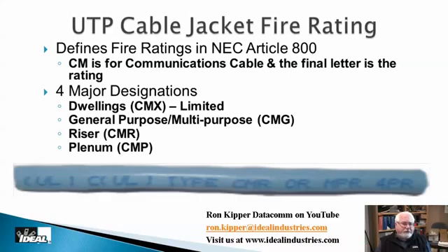Inside of walls, as a general rule, you're going to be told to run riser-rated cable, and you'll find it will say CMR on the cable someplace. CM stands for communications grade cable, by the way. It might say MPR, which is multi-purpose, but the last letter is the one you want to know, which again tells you what its flame rating is.